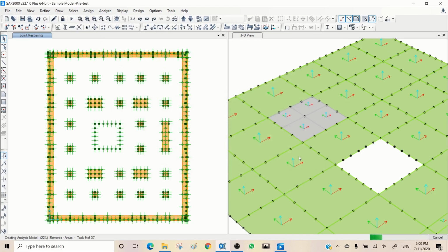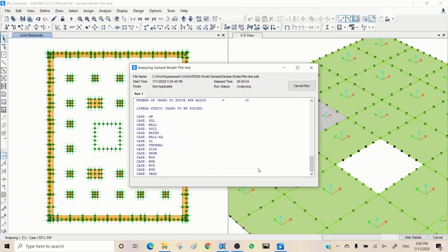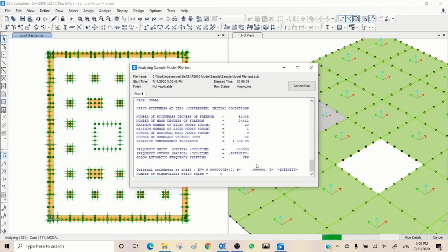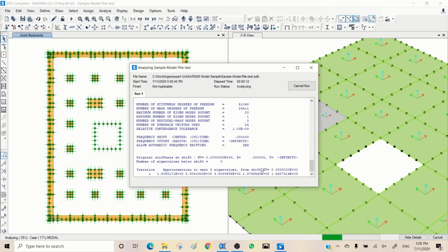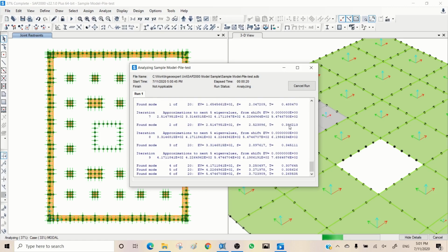And see what would be the difference in period. It could be sometimes up to half, depends on the type of structure and the flexibility and ductility of the superstructure. Because this structure is very short, I wouldn't be surprised if the first period is something about 0.5 seconds. So let's see what's coming up. Even here you can monitor it and see the result. Okay, the first period is 0.48, so it's shifted.